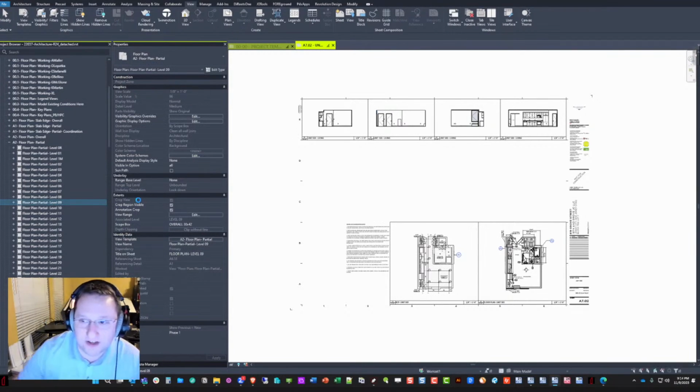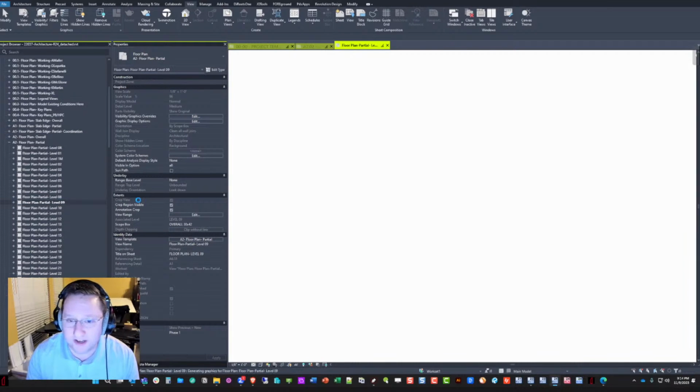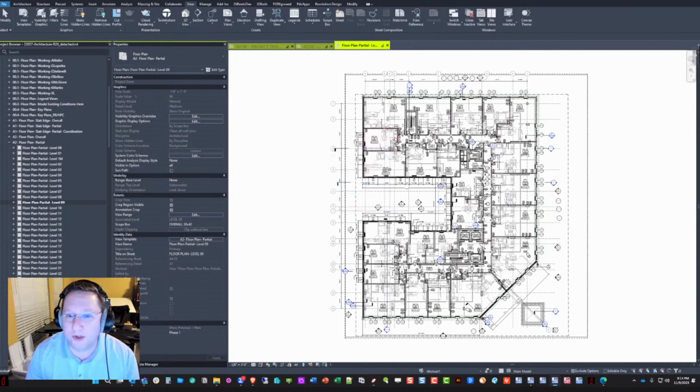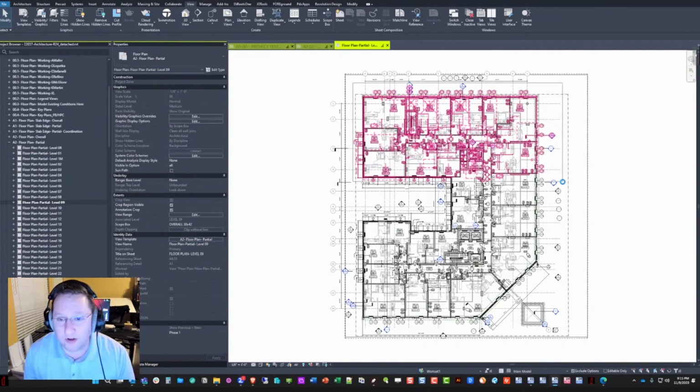So imagine you had to change a floor to floor height. And Revit did the nasty fixed groups thing, which, newsflash, it'll do every time you have to change a floor to floor height. And you always hit make new group types because ungrouping is the death of your project. So now you have a whole bunch of groups that have the stupid number 2 at the end, and you have to go find them all and replace them. So Filter More is a tool that will actually replace the regular Revit filter if you choose to let it.